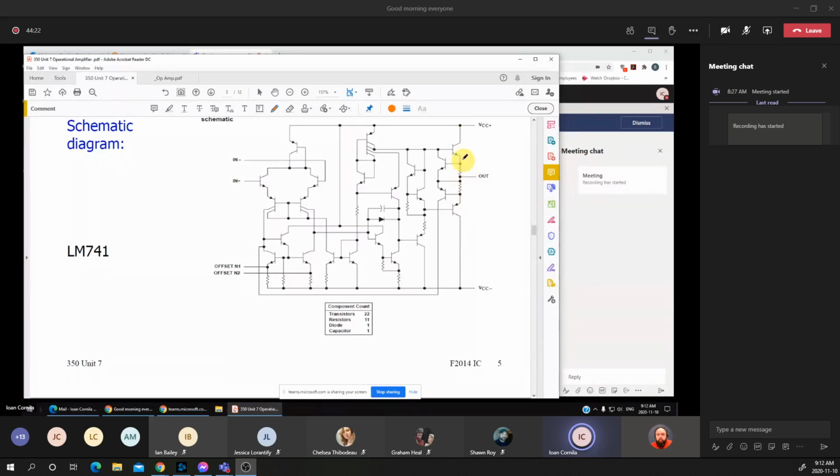And the two resistors that are added into the emitters of the last stage, which is the final stage or the push-pull circuit, actually limit the output current. Those two resistors are used to limit the output current, and it also has short circuit protection, having those two resistors and the other two transistors that are connected across the two resistors on the output.